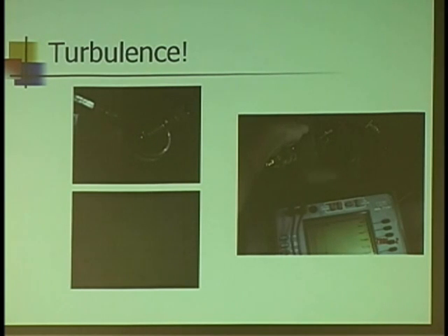Does a valve rotate as it runs? Every once in a while, I've got the valve rotating into a position where it was not sealing. So all that combustion pressure is trying to rush back out of the valve. As it does so, it creates a lot of turbulence at idle inside the combustion chamber, and it literally blows the spark around.